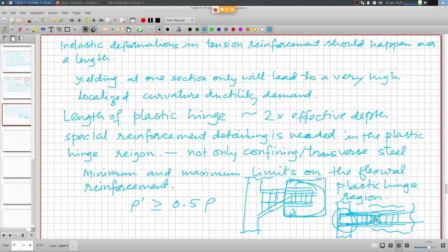And in order to provide protection against that, it is also recommended that some shear capacity should be built up by bending these bars by 45 degrees in both directions. Bottom bars should come to the top at the end, and top bars should go to the bottom at the end, so that this diagonal steel will arrest any tendency for sliding shear, right?